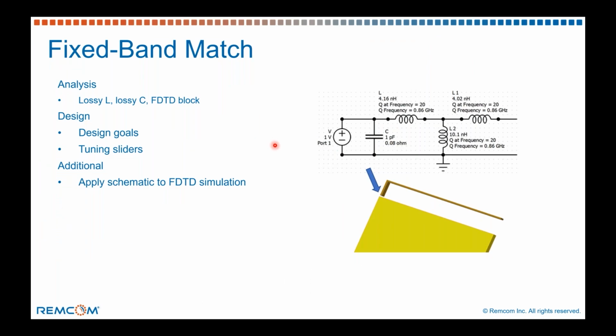So that wrapped up the first example. I just introduced you to the schematic editor, showed you how to build out a schematic, how to include the XFdtd block. We went over design goals and tuning sliders, and then how you can apply that back to the XFdtd simulation.